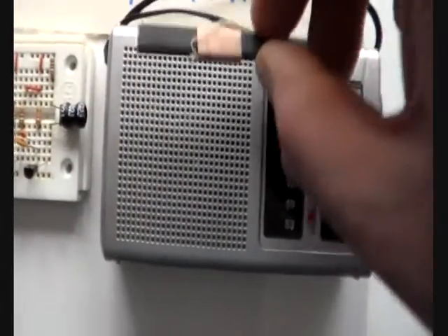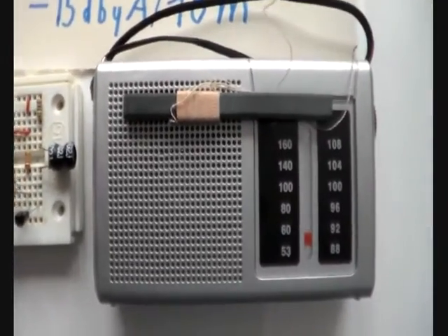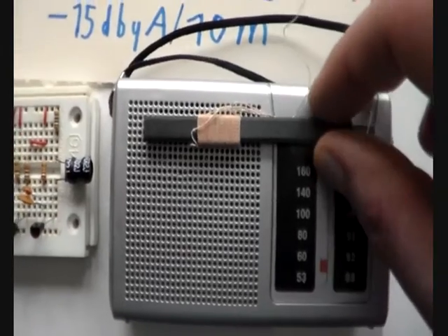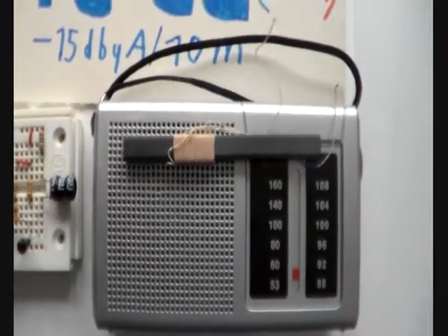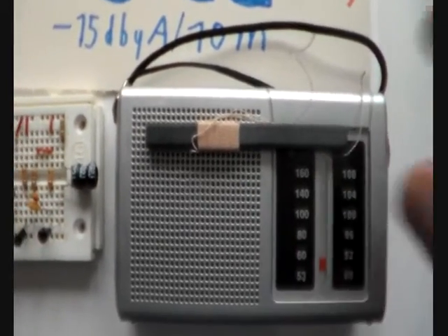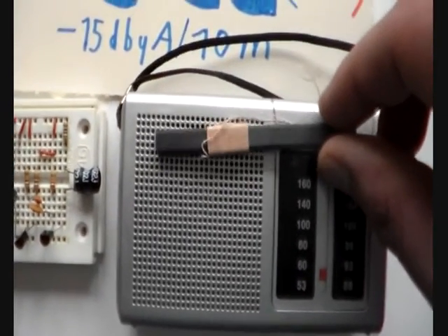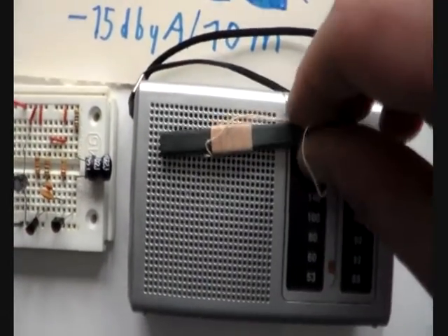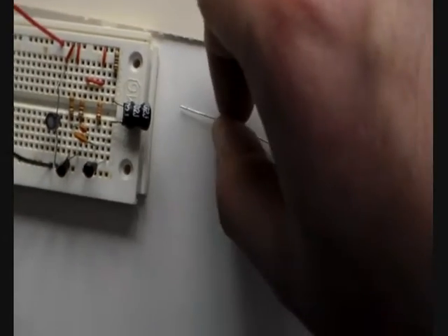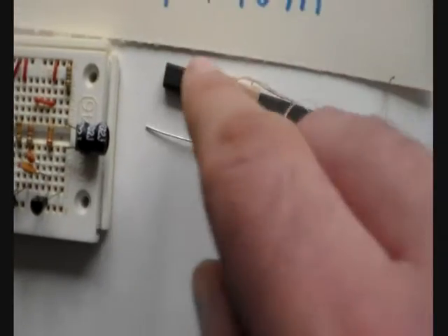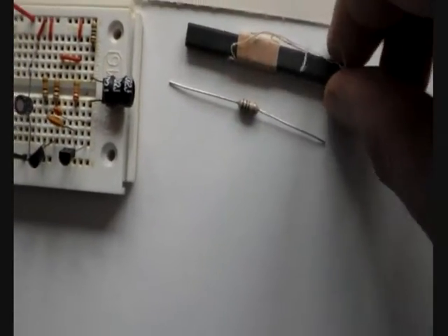So here I can tell you, in these radios there is one of these ferrite rods. Each portable radio has one of these ferrite rods inside. Not this one. It could be a little bit smaller but therefore thicker. Also the coil could look different, but basically all are using this ferrite antenna. So they have a coil and a ferrite rod. The transmitter is going to use this type of coil. It looks like a resistor, but it's a coil. This is basically the same thing as this one, just small.